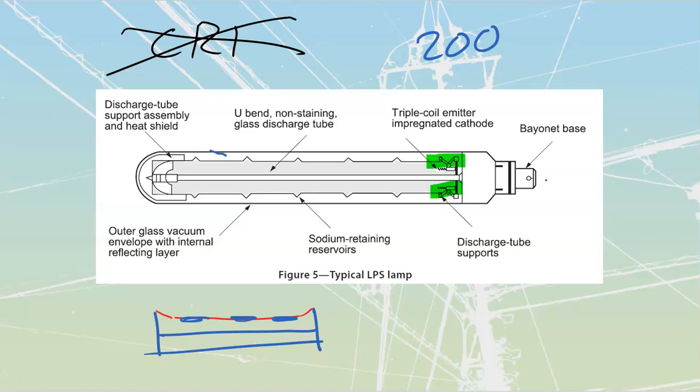Not really. I mean, we talked about disposal. At the very end of these ones here, they talk about that these ones have got a high amount of sodium metal. Any type of fluorescent, doesn't matter whether we're looking at a regular fluorescent or HID fixtures, should be properly recycled, because the substances that are inside are hazardous. And first of all, we don't want to dump them into the environment. Secondly, it makes the rest of our industry function much better because it's easier for them to be recovered and put back into new components.